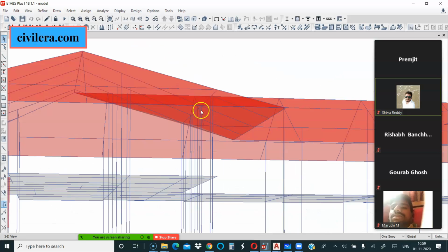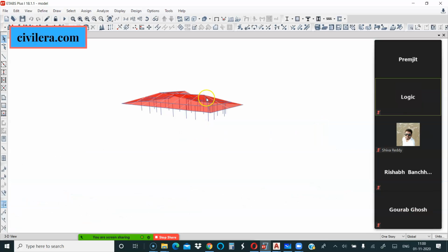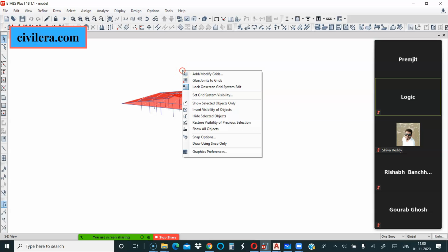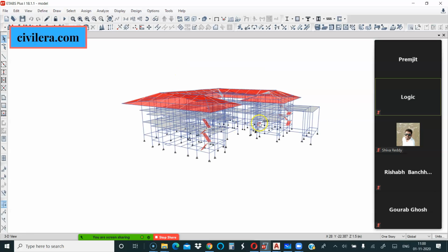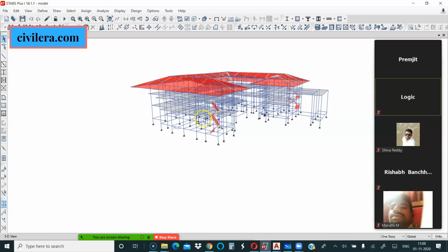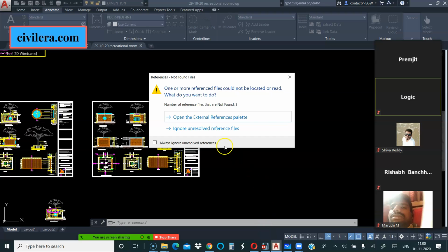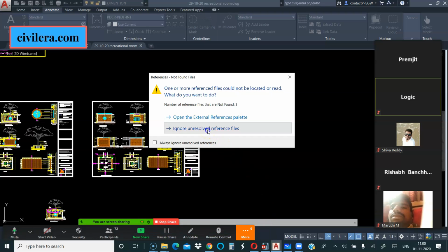Okay, I will select the roof area alone and then just show you. These are all thin shells, meshed to achieve accuracy. So that's how I have done that. Now, once you model up, before that you will have to decide your column positions, keeping in mind it's a demanding structure where you might need some long spans.